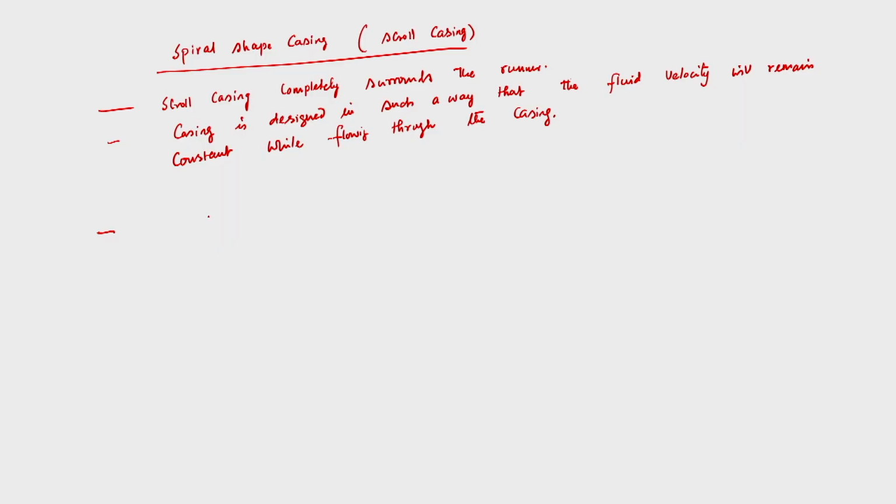And the second thing is, whenever our working fluid is passing through the runner, the working fluid will be deflected because of the runner blades, whether it is water or any other working fluid, and so the velocity of whirl will decrease. This is very important. So I am writing, this is the overall situation.